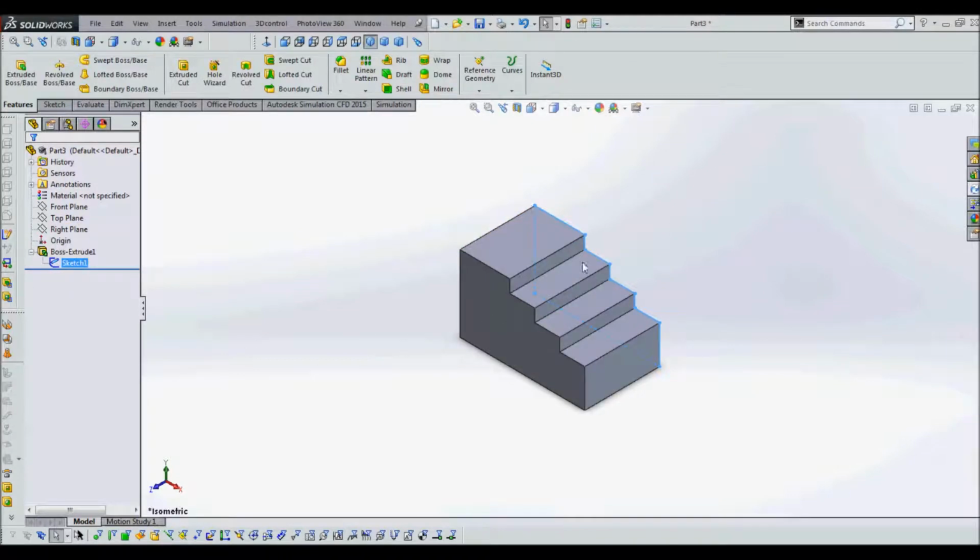You can see it's highlighted around here on the outside that we extruded from. And this will continue to develop as we work on this part more. So the next step is to make some holes in the cannon base. This is what will allow wheels to go onto the cannon base as well as allow the cannon barrel to pivot. So for making our next sketch, we're going to go back to the Sketch tab.